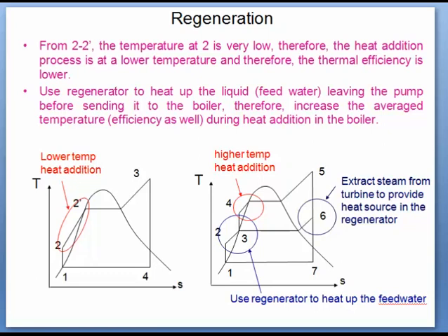This is accomplished by extracting steam from the turbine to heat the feed water. This also we had seen in our earlier discussion, where we were using LP heaters and HP heater, where the feed water is sensibly heated, and for heating, the extractions are taken from the LP turbine, IP turbine and HP turbine.